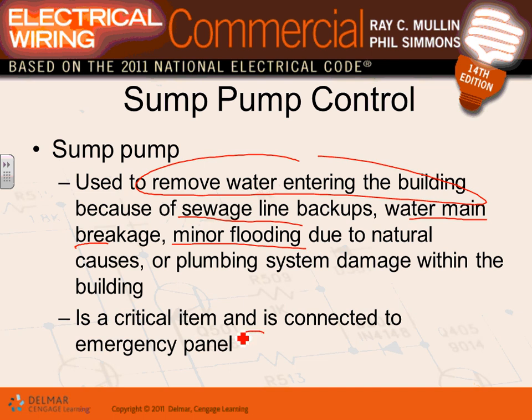It is connected to the emergency panel. When you say emergency panel, it has to come up within 10 seconds, guys. But typically, if you have a pump in a commercial building, it's a legally required standby system, and it has to be backed up by a generator. The generator has to come up within 10 seconds if it's emergency, or 60 seconds if it's critical or legally required. So it will be fed from the owner panel, which is backed up by a generator, and that can be a standby generator. If it comes up within 10 seconds, it qualifies as an emergency source of power.